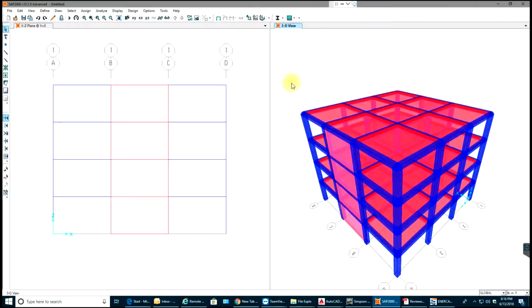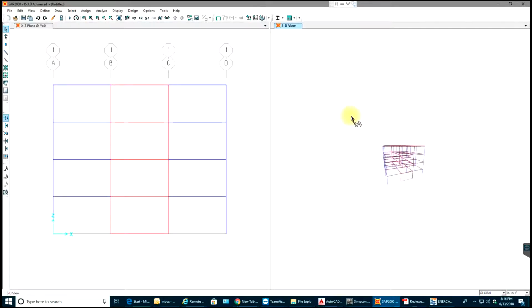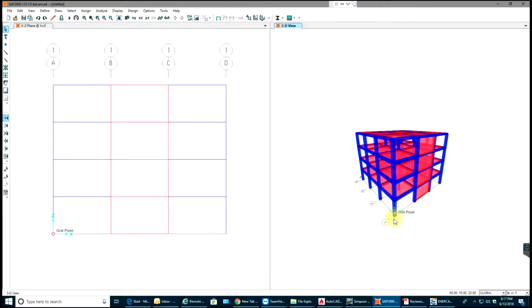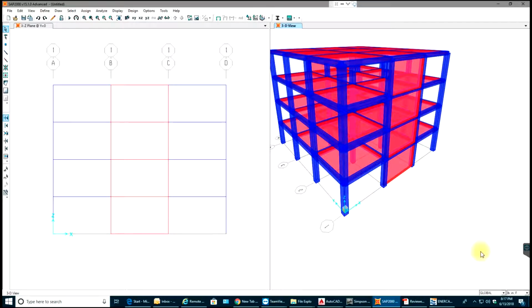Alright, never mind. Okay, coming to the point of the tutorial, I am gonna apply the area wind load on this walls and on the walls on the other side. So let me just, oh wait, do not play with me. Alright, so this, oh my god, my mouse is so sensitive. So this will be my windward side, nothing but my positive y direction, and the other side will be my leeward side, nothing but my negative y direction.